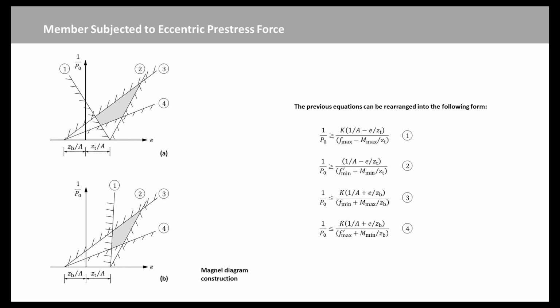The Magnel diagram is a powerful design tool as it covers all possible solutions of the inequality equations and enables a range of prestressed force and eccentricity values to be investigated. Values of minimum and maximum prestressed force can be readily read from the diagram, as can intermediate values where the range of possible eccentricity for a chosen force can be easily determined.